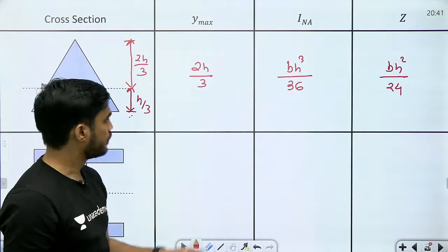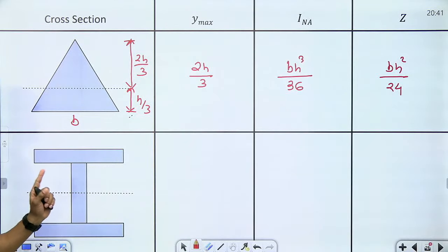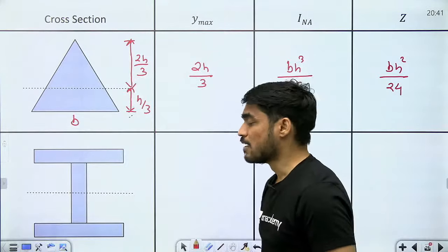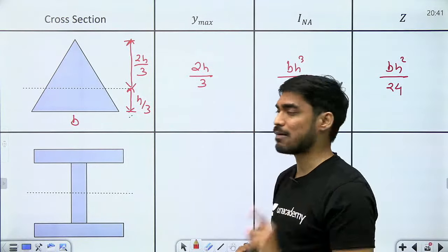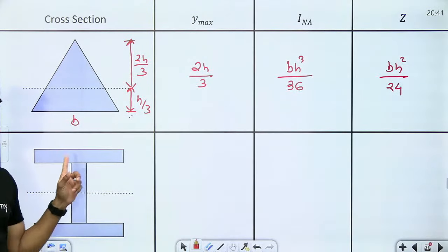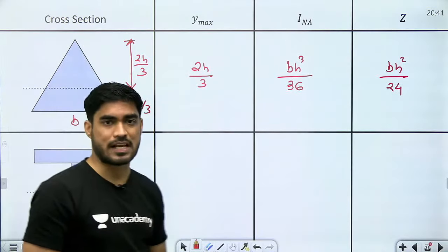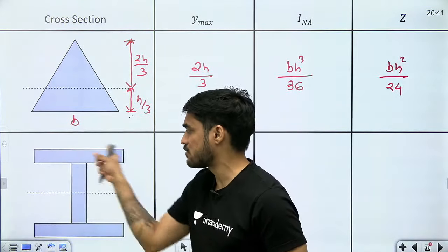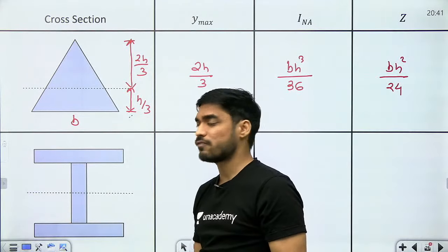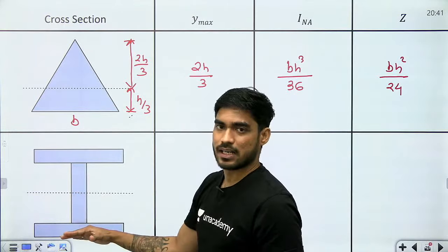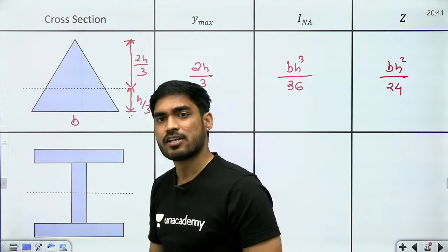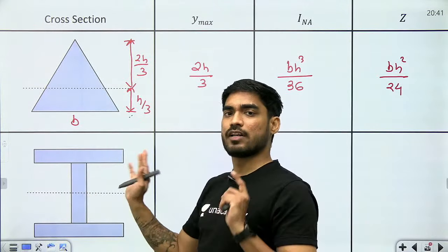Yes. Now I section. अब I section के लिए भी आप moment of inertia की equation याद रख सकते हैं। कैसे बेटा? I section के लिए भी moment of inertia निकालना बहुत आसान होता है if it is a symmetric I section. Symmetric I section means the flanges are equal, equal flanges होने चाहिए top पे और bottom में। This is known as flange, this is known as web, the vertical part is known as web, the horizontal part is known as flange. So if the flanges are equal then it is a symmetric I section, means this neutral axis will be at the center.